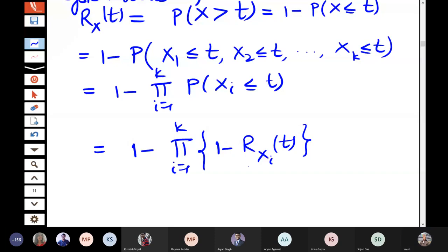Let us take the previous example where I considered 0.9. Now here you see this product will be decreasing, and then you are doing 1 minus, so it will increase. So when you add components connected in parallel, the reliability of the system improves.